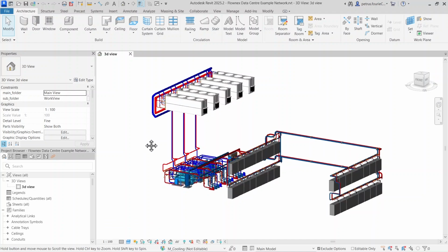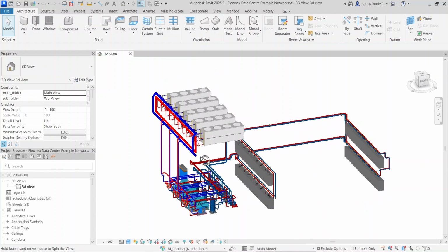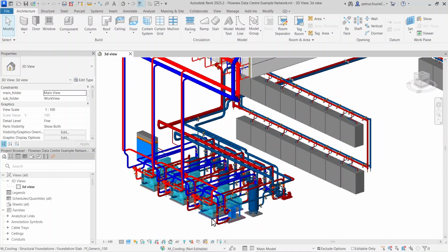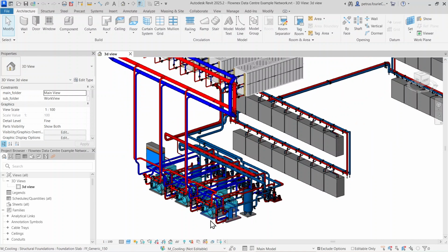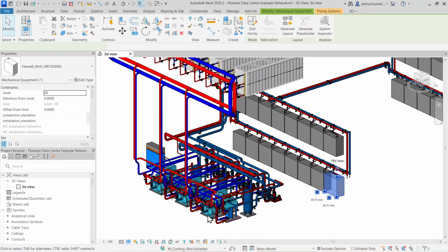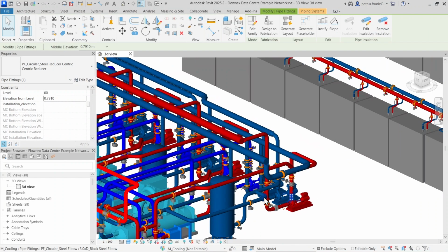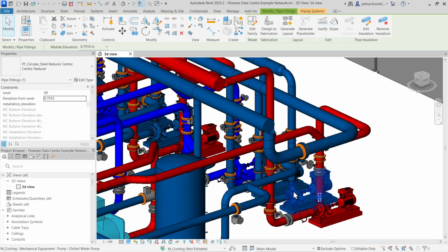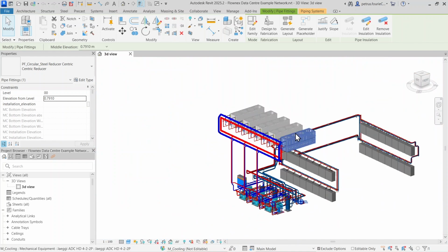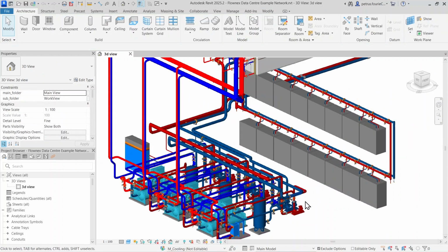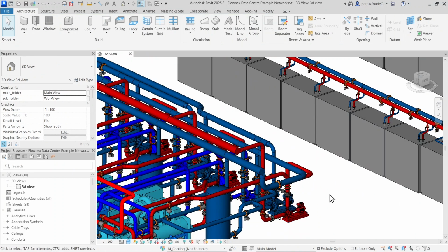Before we get into the detailed workflow, I just want to explain the system we are looking at. This is a hypothetical setup that has all the typical features and components of a modern data center thermal management system. There are 2 data halls with 16 CRAHs each, 3 water-cooled chillers with buffer tanks and evaporator pumps, and 3 sets of distribution pumps to supply water to the data halls. To reject heat to the environment, there are 5 dry air coolers on the roof with condenser pumps to move water from the chillers to the decks.